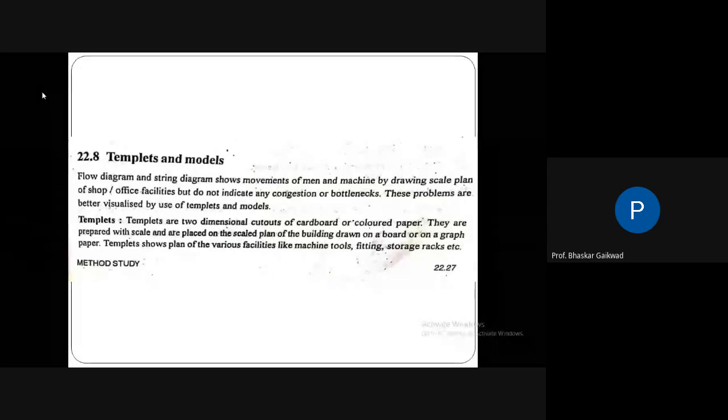then you can see that various types of slats are there. Maybe bagasse carrier slat or cane carrier slats. It is there. But while manufacturing, as per the drawing, in order to check by using attribute type of inspection, we require certain templates, certain gauging systems, and the workers gauge the manufactured part or this slat or the bagasse carrier or cane carrier slat by using a template.